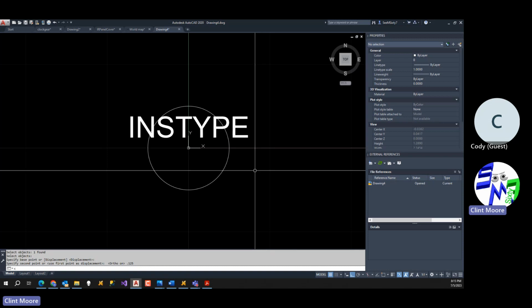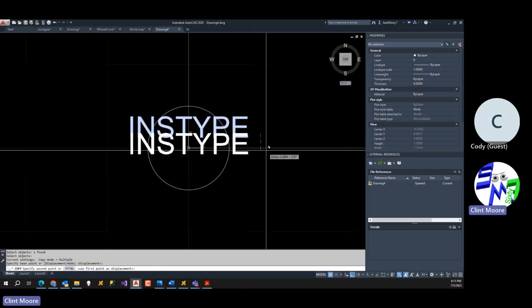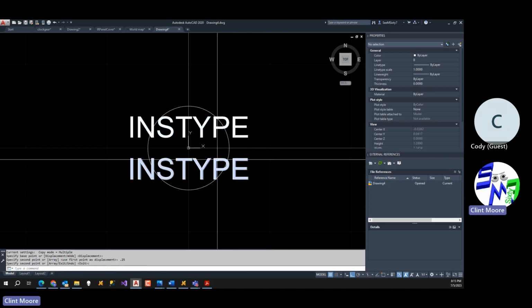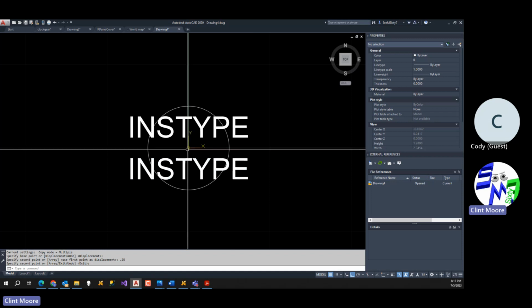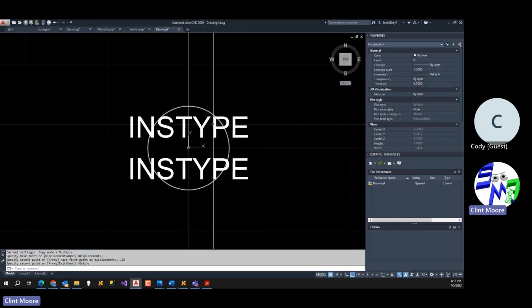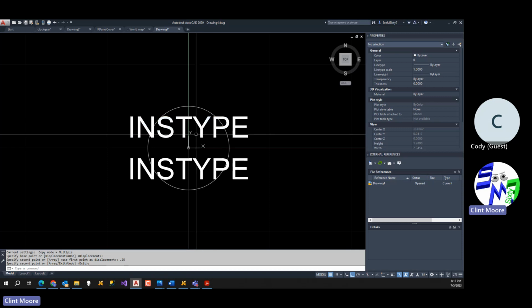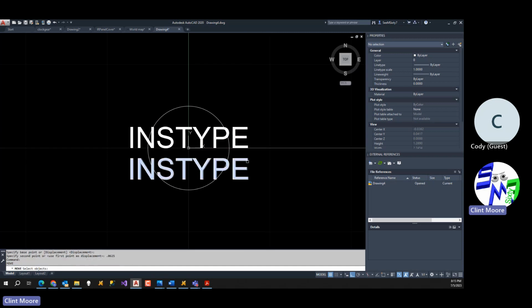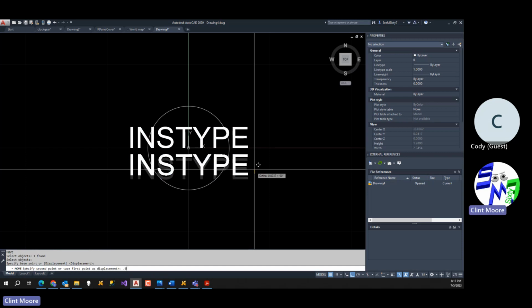Now I'm going to copy this from here down 1/4 inch, 0.25. Boom, and now I look at this and I'm like, okay, I could probably close this gap a little bit so I have a little more room, because you see how quickly the arcs start to encroach on your line, on your text. So I'm going to move this down 0.0625 and try that. And I'm going to move this up 0.0625.